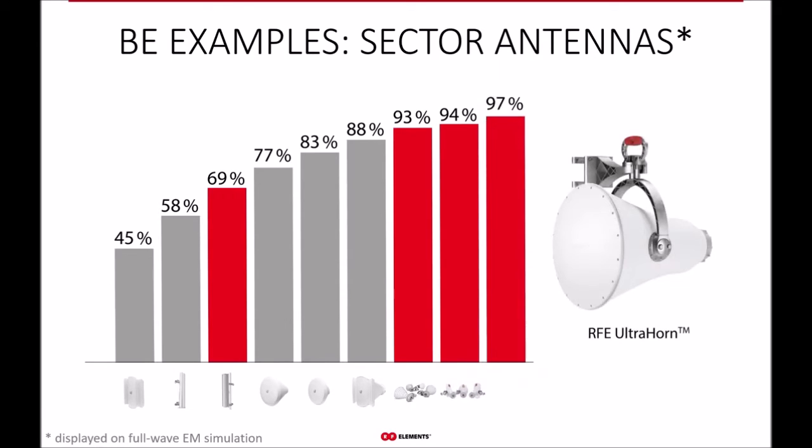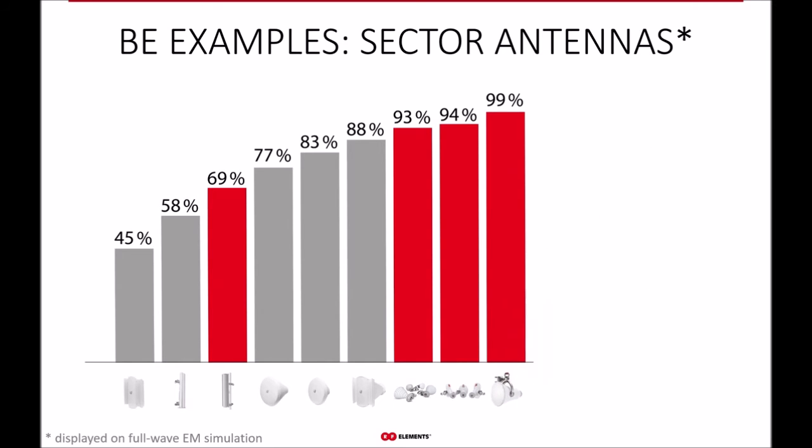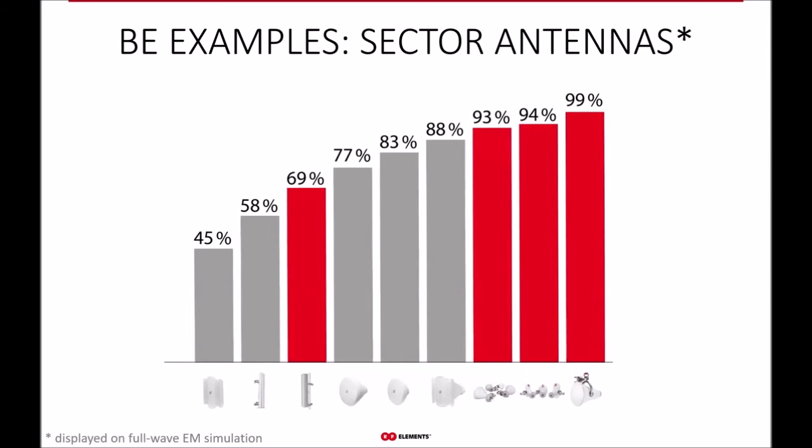You can actually also see other horns in this graph as well. And this is to highlight that it takes a considerable effort to design a horn antenna so that its beam efficiency is high. So the stable and 0 side lobe performance is not a given, is not a default when you have a horn. And if you want to know more about beam efficiency, we have a whole webinar about this topic, which we did some time ago. And you can find the recording of that webinar on our YouTube channel.